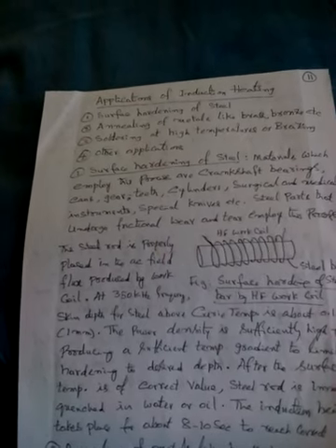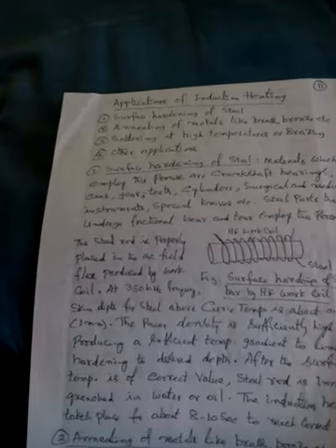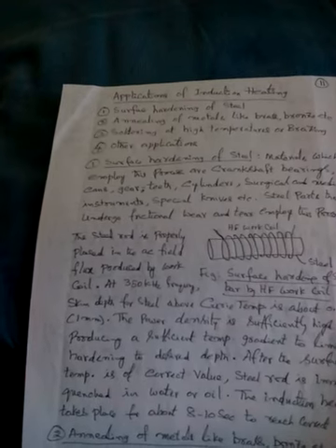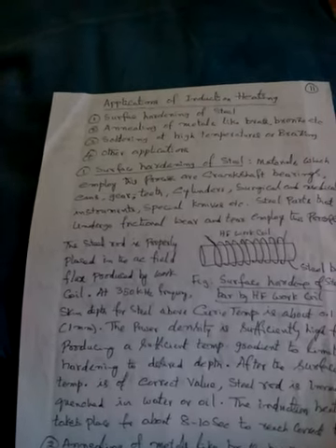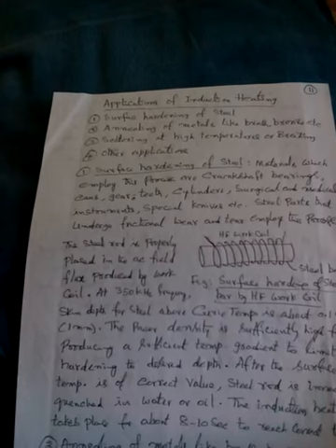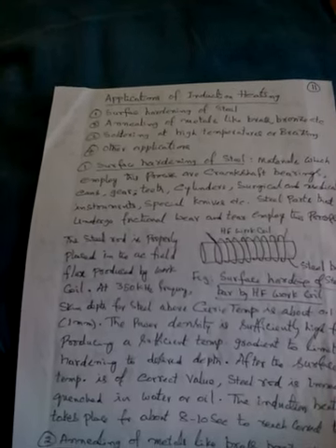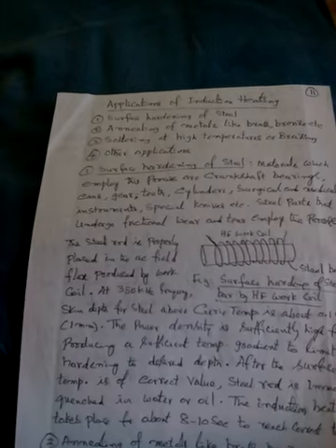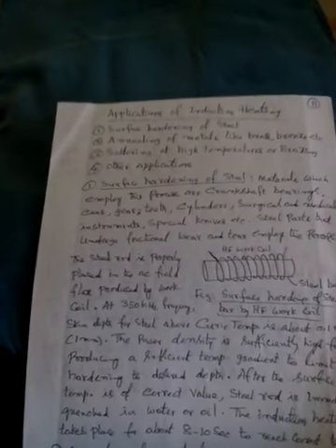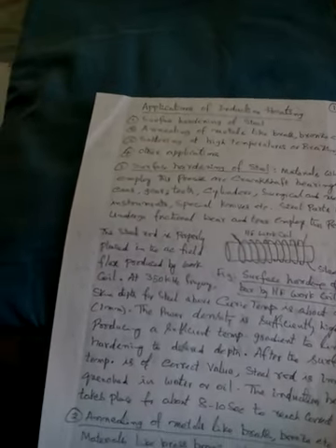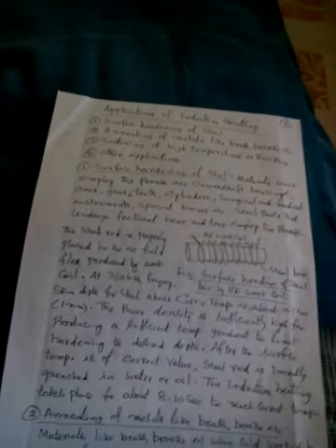That's why we can harden a number of steel rods in a short period. We can make it automatic also, because the timer is fixed, and when the desired temperature is reached, the timer is automatically switched off, and the next rod goes into the coils, and that's how it works.